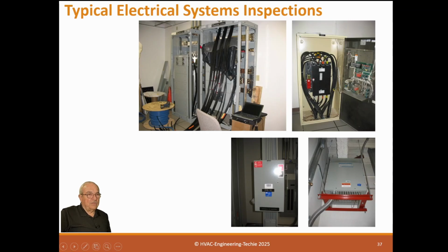This is another pull station coming in. You see this is pull. This is an ATS switch. And this happens to be a bus, a vertical bus. Sometimes if it's a high-rise building, they'll use a bus like this, a vertical bus, and they have switches on the vertical bus that pull power off instead of using conduit cable. Transformers can be mounted high, not a problem. They just have to be accessible.